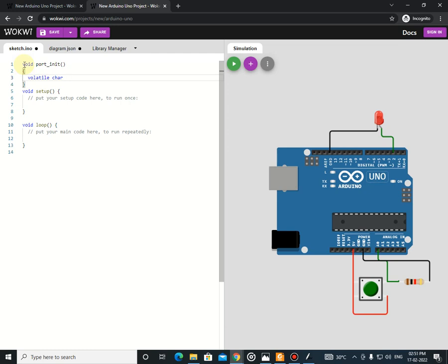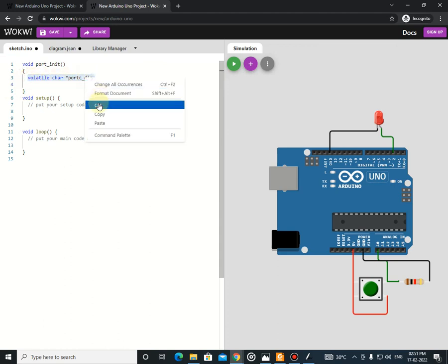So next thing I'm going to use is the direction registers' address. I'm going to declare pointer variables named port C direction and port D direction, since I'm going to use two ports and want two declarations, the port C and port D direction registers.